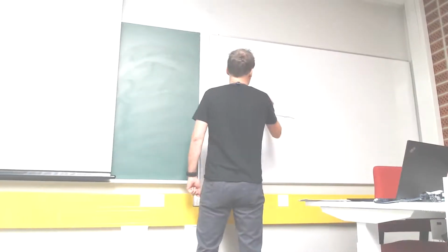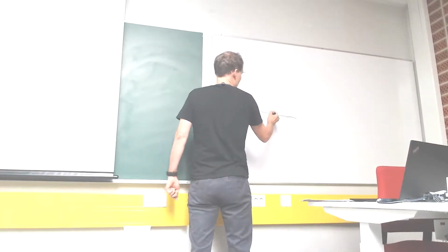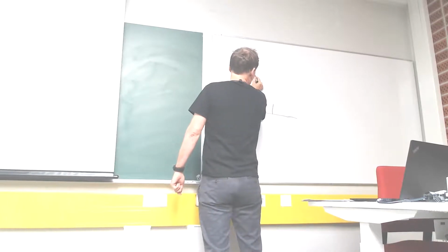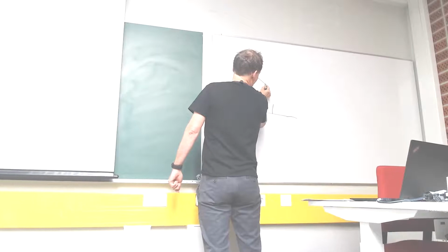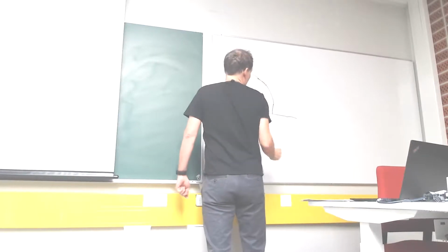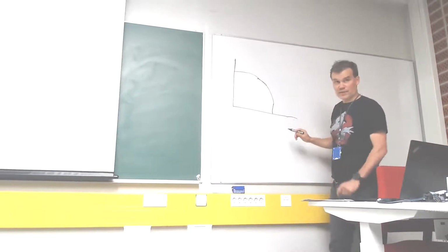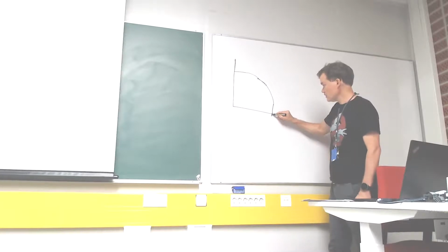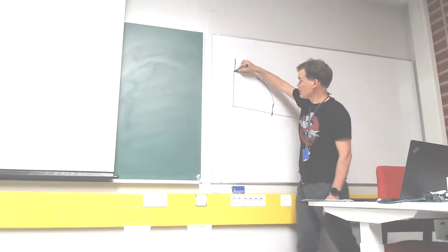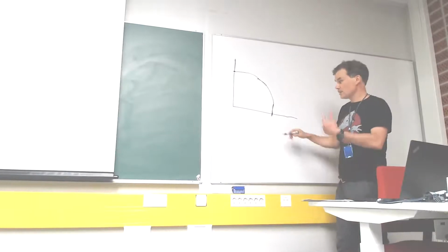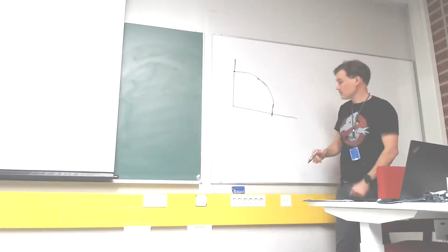Okay. So if you're plotting the rate region for the uplink first, we'll have this type of shape. And this is with individual power constraints per user. The rate per user is upper bounded by the single-user capacity using that power.